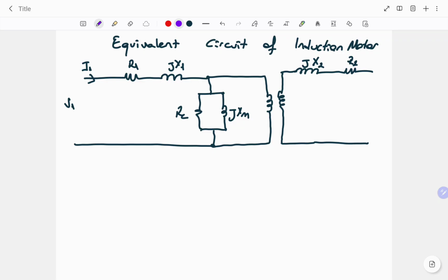If you remember, in the rotor part, we have short circuit rings through the rotor conductors. So because of this, we will add a short circuit cable to the output side, because we will not get the electrical energy from the output. We will take mechanical energy through the R2 resistance.